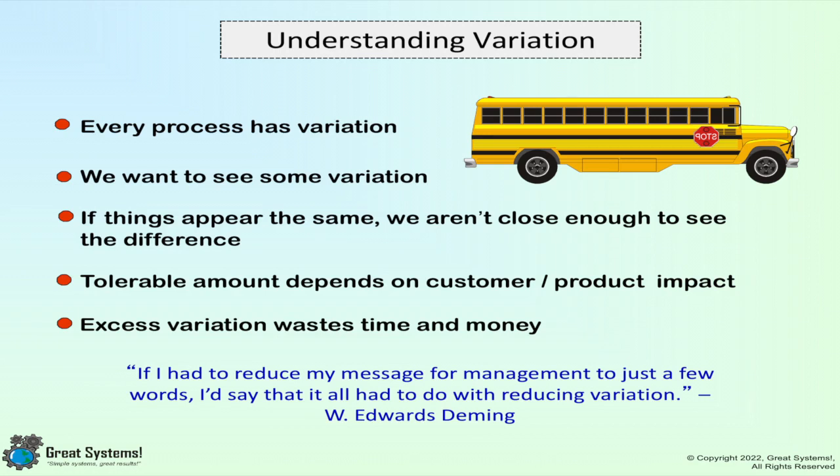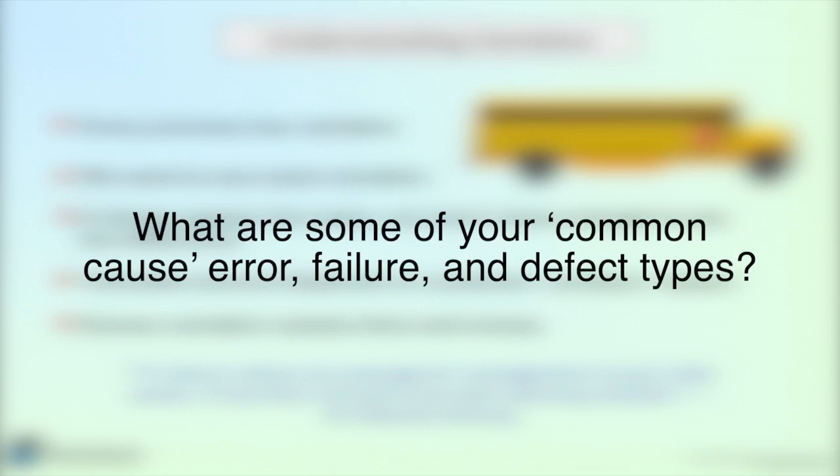If we understand a system, we can predict within a range of values how it will perform. This range of performance is known as variation, the difference between the lowest and highest values for a majority of the results produced by a process when it is measured. All processes have some degree of variation, but this amount can be large or small. Sigma, or standard deviation, is used to measure variation, the width of a process.